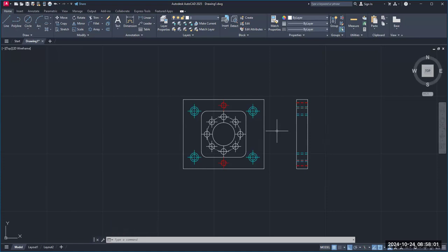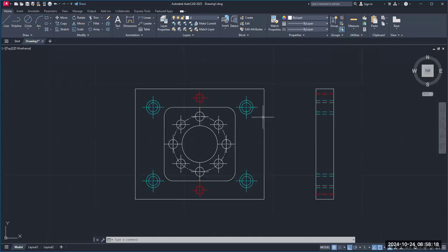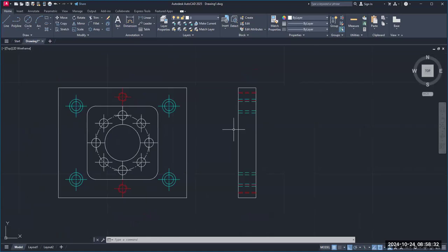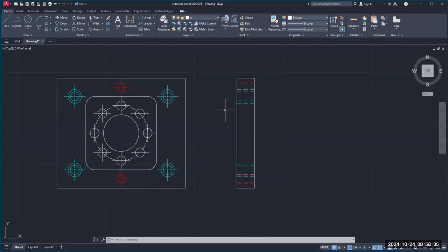Okay, we're not done because the counterbore hole, the large diameter part goes 0.25 deep into the part. The larger hole is 3/8 and the smaller hole is 1/4. The 3/8 hole does not go the whole depth. It goes 1/4 of an inch, but the 1/4 inch diameter hole goes all the way through. So how we do this, Mr. Morris? Well, you can come up here and use the offset here, or you can click on offset.